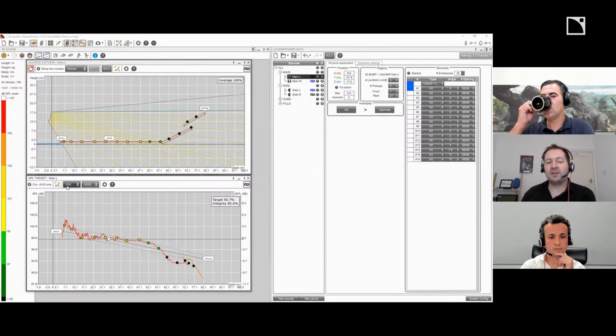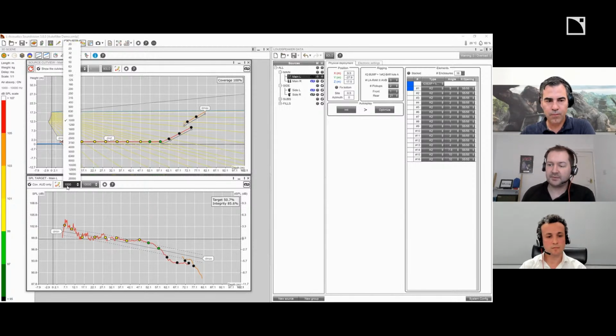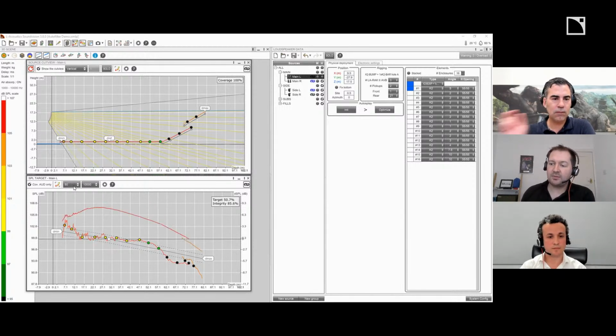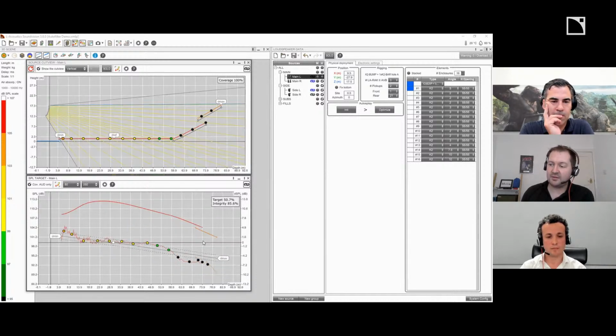We also want to view the low frequency response. So here I'm going to select 80 to 250 hertz, and I'm just going to resize this scale. So now we see we have the LF frequency response over depth of the audience and the HF response.